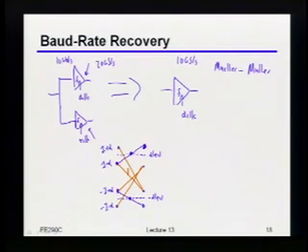Okay. Now, to be totally fair, that actually obviously depends upon the value of alpha, right? Because you can imagine if alpha was really big, then actually the edges you get from these other transitions might actually be better, right? But typically, let's say for a reasonable channel, that's probably not going to happen. In most cases, in particular this edge and this edge here, would actually have much better slopes on them, okay?